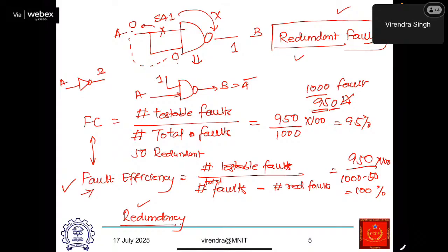The D algorithm is much more difficult and it will take much more time. But in the PODEM algorithm, we go back all the way to the primary input. And now, to declare a fault is a redundant fault, in the worst case I may need to explore all possibilities at the primary input. I have to build the entire computation tree at the primary input.